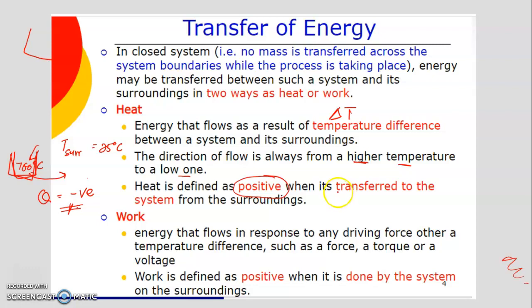And then work. Work is defined as energy that flows in response to any driving force other than a temperature difference. Other than temperature difference, you may consider the transfer of energy as work, not heat. If it is a temperature difference, that is heat. For example, force, torque, or a voltage.